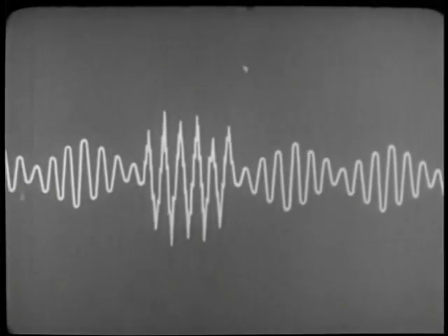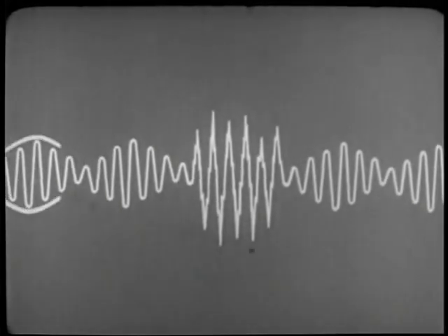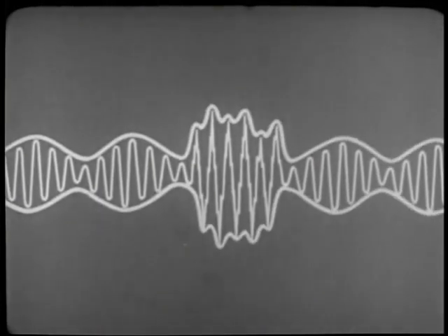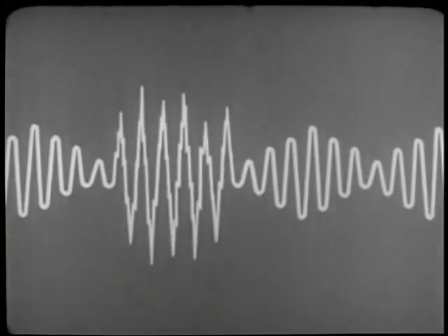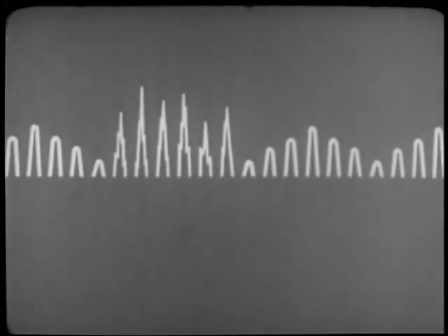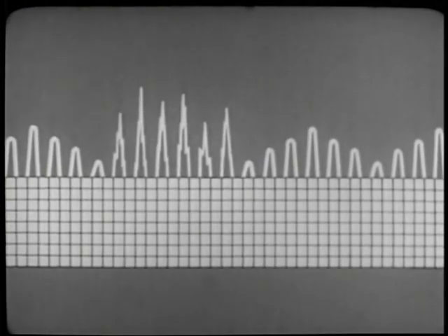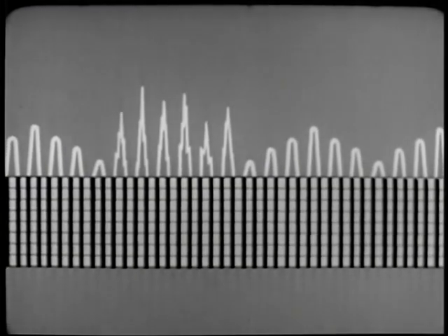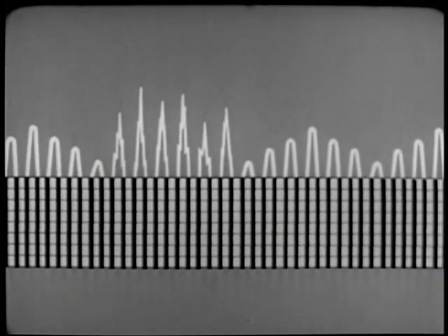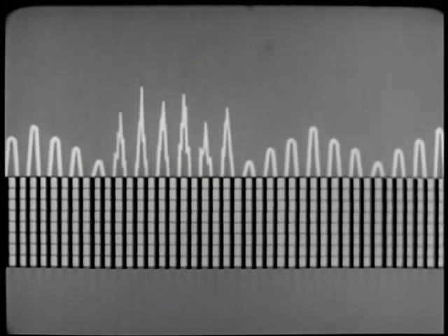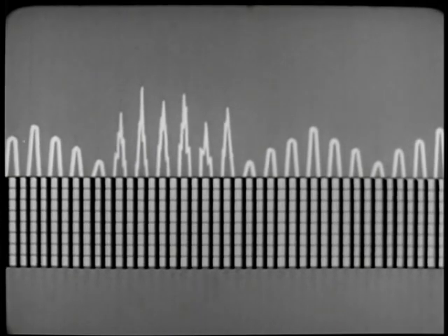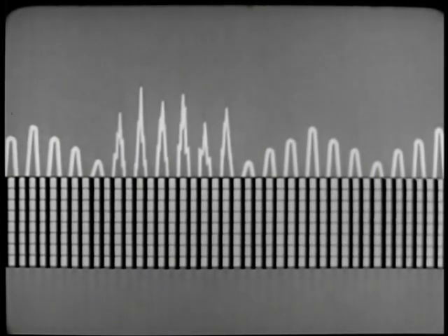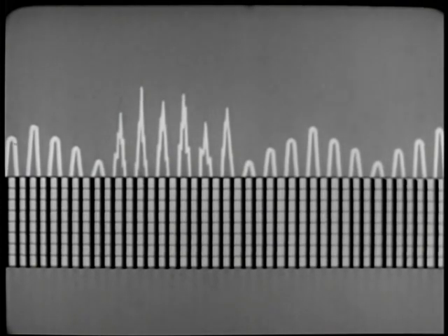Before considering the AM receiver, notice one fact. The electrical disturbances alter the amplitude of the RF, but they have no effect upon its frequency. An important point to remember is that the distance between each wave is identical. The receiving antenna will pick up both the composite RF waves from the transmitting antenna and the random noises generated by the lightning. These two will combine and distort the amplitude of our desired signal, but the frequency we transmit is unaltered, unaffected by disturbances.